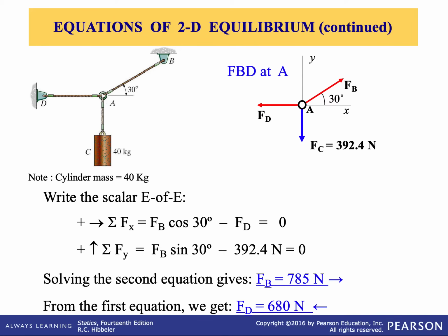So this is how we actually analyze static systems at equilibrium. Step one, you need to build a free body diagram. And then you need to locate all the known and unknown forces. And then you need to resolve your forces into x and y components, the Cartesian components.